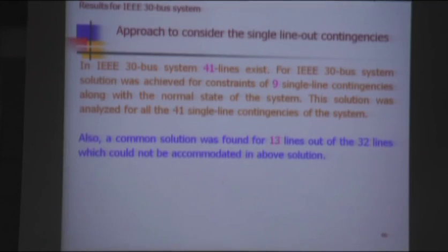Again, the problem is not only of these primary backup constraints and the sympathy trips. The problem is more complicated. For example, let us talk about some area. Suddenly some area gets isolated. Now when some area gets isolated, the settings of the existing relays are still not changed.